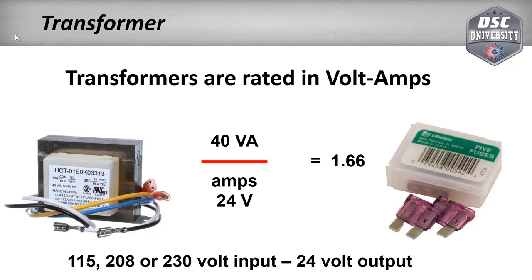That way we don't have 115 volts going to a thermostat up in the living space where somebody can take the cover off and get in there and could get shocked or whatever. 24 volts will still shock you, but it's not going to hurt you that bad. Just catch your attention real quick.